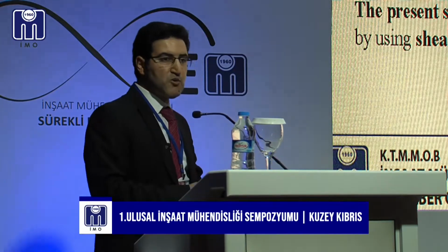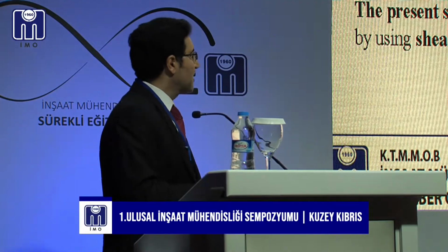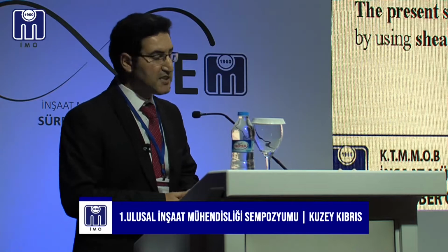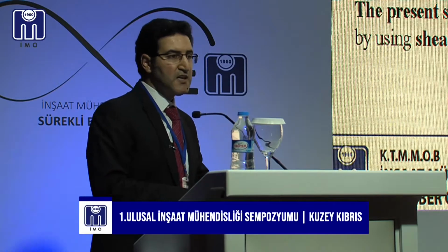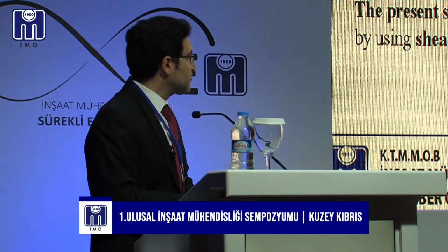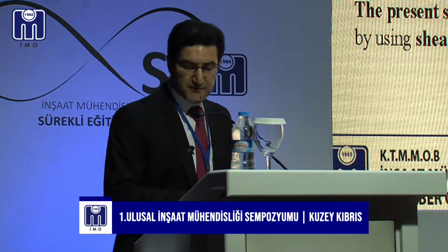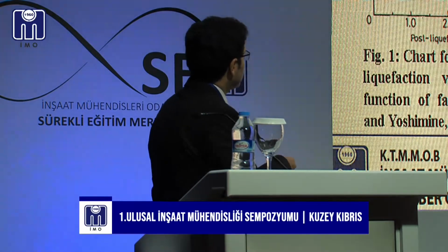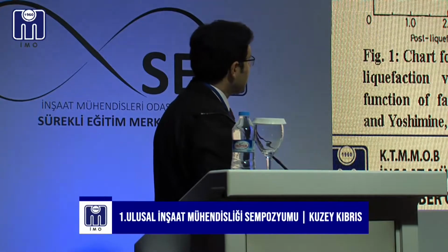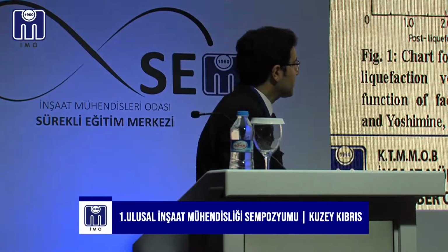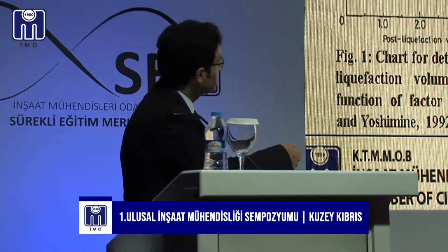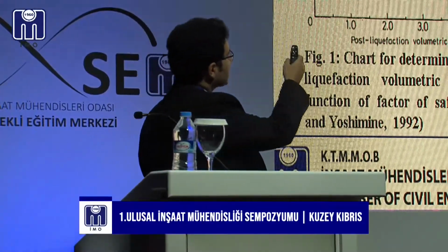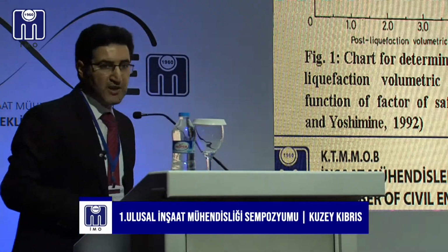For this study, we want to introduce a methodology for determining liquefaction-induced settlement based on the shear wave velocity, in terms of maximum shear strain and the factor of safety. This is the literature review of the paper by Ishihara and Yoshimine, and this is the important parameter: as you can see, the factor of safety versus the post-liquefaction volumetric strain.